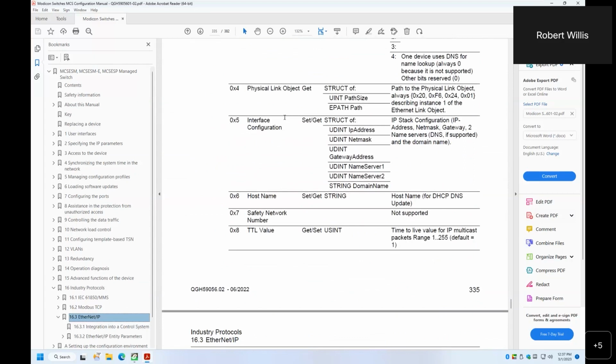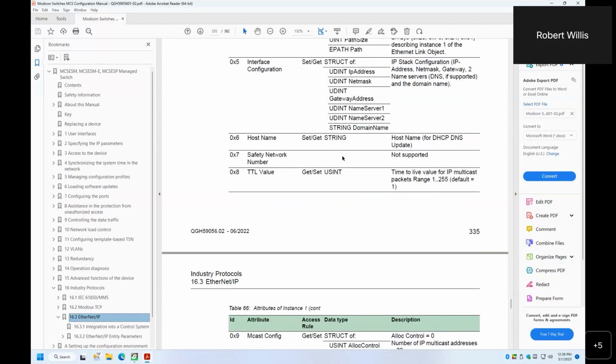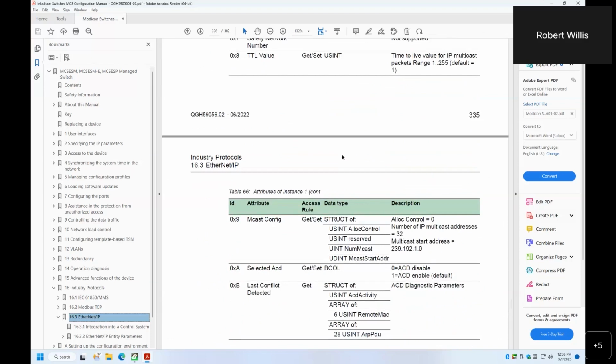So the information you bring into the Modicon M580 might be a subset. It's only what I need in order to manage the application. While a SCADA system comes in and gathers additional information that it might want to present to the user, and an SNMP device can go in and gather some additional information specifically related to the network. So I'm not limited to just one device talking to me. So this is in here.